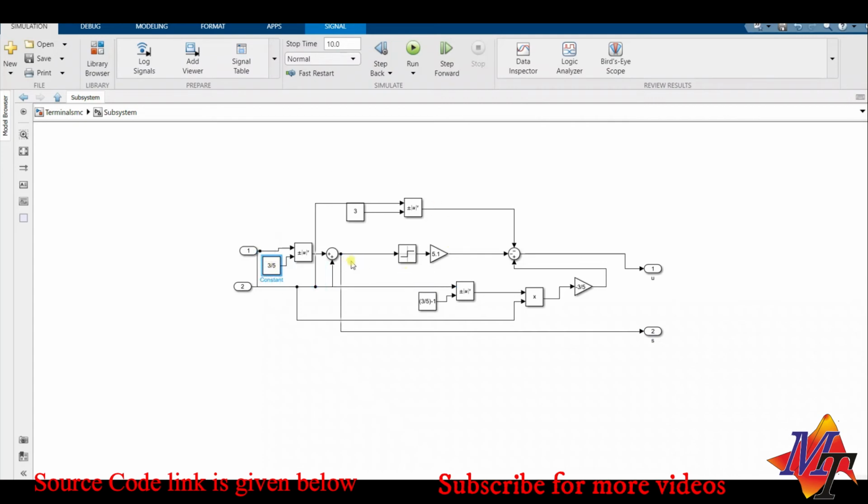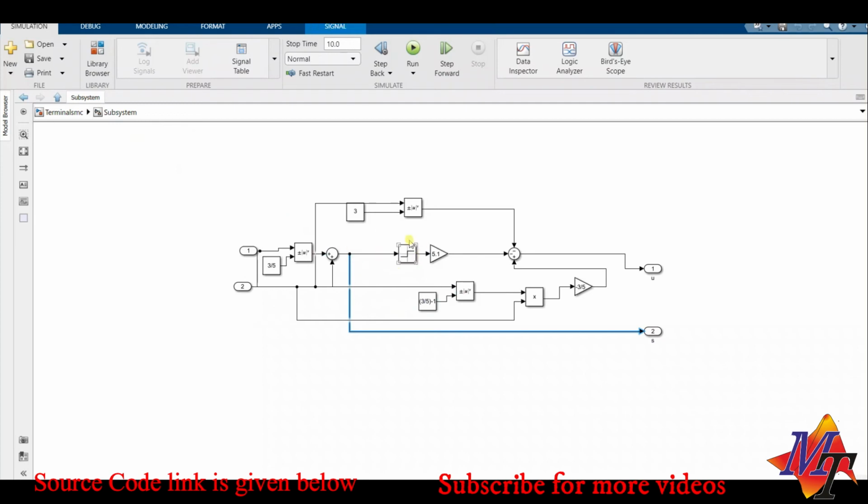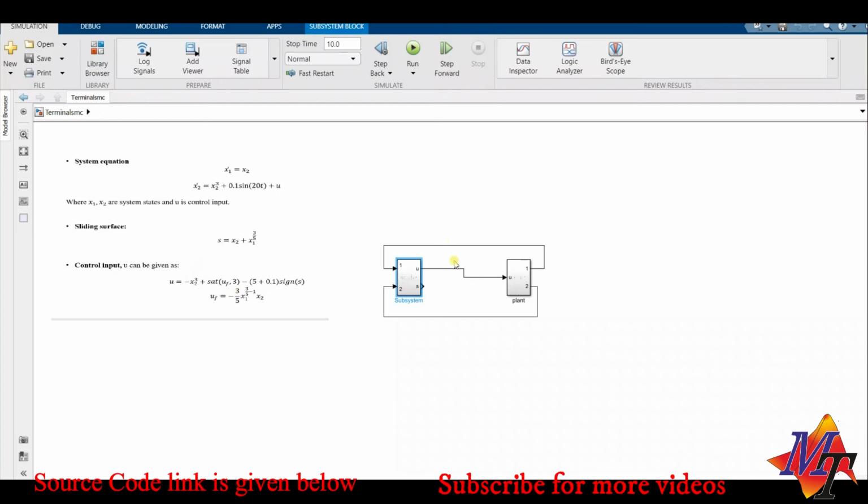So we have got here, first we have taken the sliding surface, that is a combination of x1 and x2, that is x2 plus x1 raised to 3 by 5, that is the sliding surface. Now for the control input we have minus 5.1 sin s. So for that, as we have taken the sign function of this, passed into 5.1, and we have taken it minus, that is the first component of u, that is u equivalent. Now for another component we have minus x2 cube.